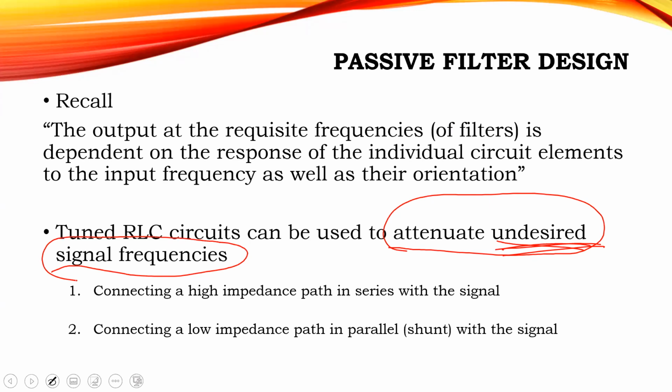We attenuate undesired frequencies by connecting a high impedance path in series with the signal and a low impedance path in parallel with the signal.